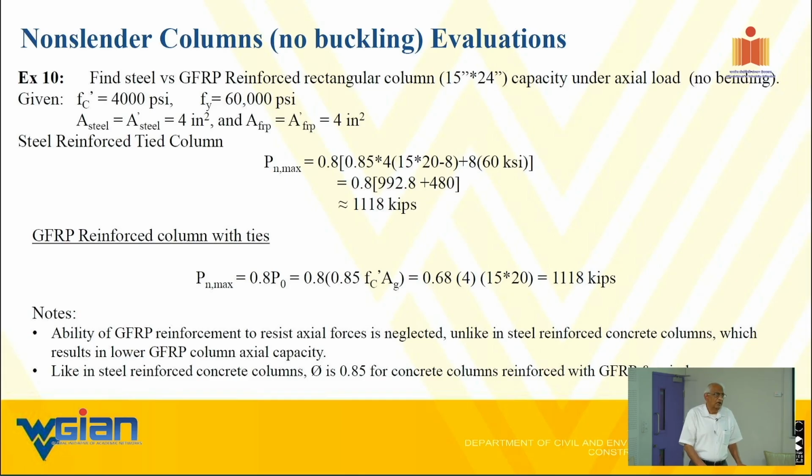That's the reason we are not able to come up with an ASTM procedure to establish it. However, the micro buckling is nowhere close when you are talking about the service loads. I mean, far from it. You understand the argument now? Yes, sir. The micro buckling is at the tail end of, exactly. Maybe it is beginning to buckle at 70 or 80%, but your service life is only at 20 or 25%. Now you got the point why I keep saying the buckling issue is an excuse.